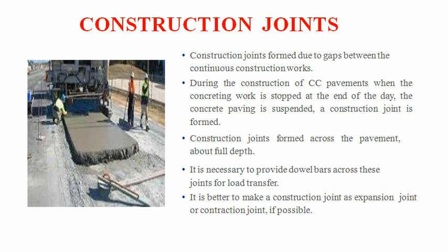these construction joints are to be formed due to the gaps which will be formed in between the continuous construction works. So during the construction of the cement concrete pavement, when the concrete work is stopped at the end of the day, then the concrete paving is suspended and a construction joint has to be provided. This construction joint is formed across the pavement about its full depth, and it is necessary to provide the dowel bars across these joints for the load transfer.